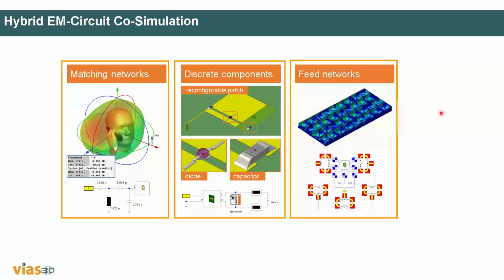But as I mentioned, an antenna cannot fit anywhere alone. Sometimes you will experience matching problems. If you don't have proper impedance matching between the antenna terminal and the coaxial cable where you are going to feed the power, what will happen? It will create a high standing wave ratio, or you could say it will create standing waves. The reflected signal will be high. Generally, our interest is below 2.5 SWR. If it goes above 5, we cannot accept it. So you may need to add a proper impedance matching network. That is one of the things.